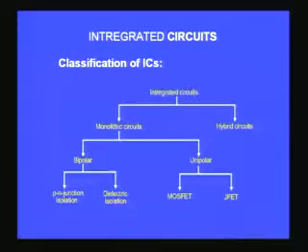Therefore, if I want to make an LC oscillator, I can integrate all the rest of the components onto the same silicon chip, and then have the inductance alone as a separate discrete unit along with this silicon chip, and together they form whatever oscillator you wanted to design. Then it becomes a hybrid, in the sense that there are two different types. You have an integrated version of the circuit, you also have a discrete version of the circuit, therefore we call it a hybrid circuit.